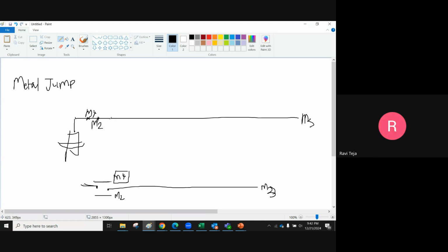One of the reasons is that M4 is a higher metal and it has a larger width compared to M3, and because of that, the resistive part of this M4 will be lesser as compared to M3. So this will create some minimization of current effect. That's why we are taking M4. Maybe one of the reasons. Not exactly. Thanks for answering.